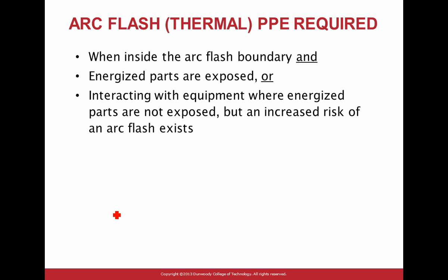Arc flash thermal PPE requirement. When inside the arc flash, you are required to have PPE under the following circumstances. If you are within the arc flash boundary. Now remember, the arc flash boundary is 4 feet unless the engineer calculated otherwise. We have software that can tell you guys. Sometimes it goes 6 feet, meaning 6 feet. Don't get into that 6 feet from the equipment unless you're working on it, unless you're dressed up.